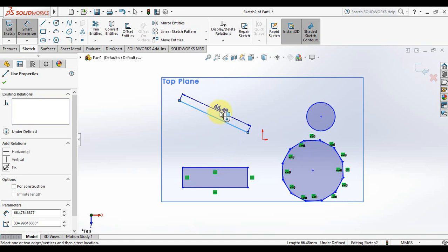What does it mean? It is dimensioning parallel to the line. If we move further, we will find that the measure changed. Now it's 6025, but that is a vertical dimension. As you can see, the lines of the dimension, the one that is here and the one that is here, are vertical. So that means that we're going to measure in a vertical way. That's why it is different. So the real one is 6648, vertically is 6025, and if we move here, horizontally it is 2810. Same thing as with vertical.